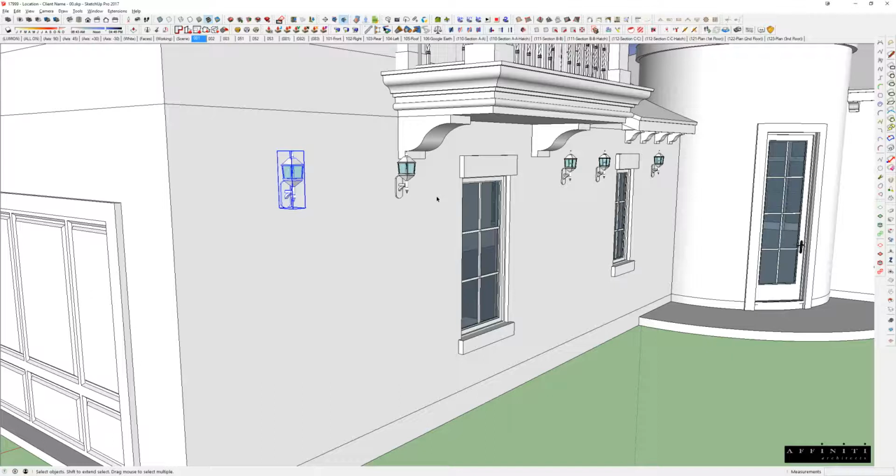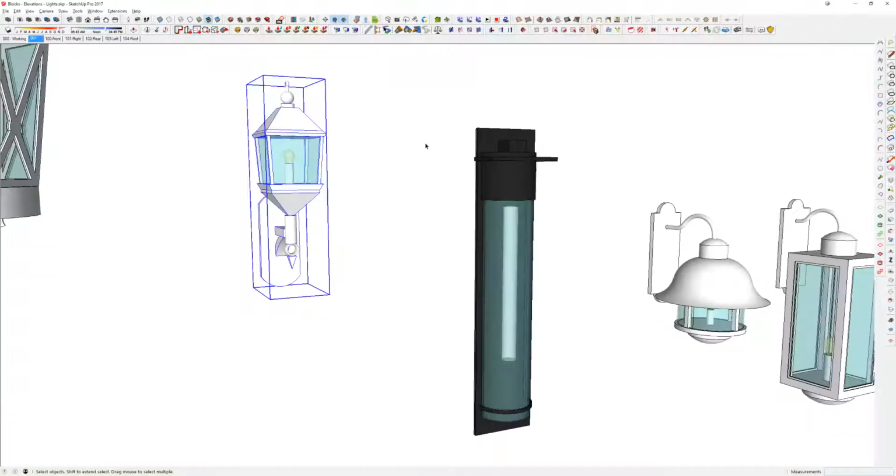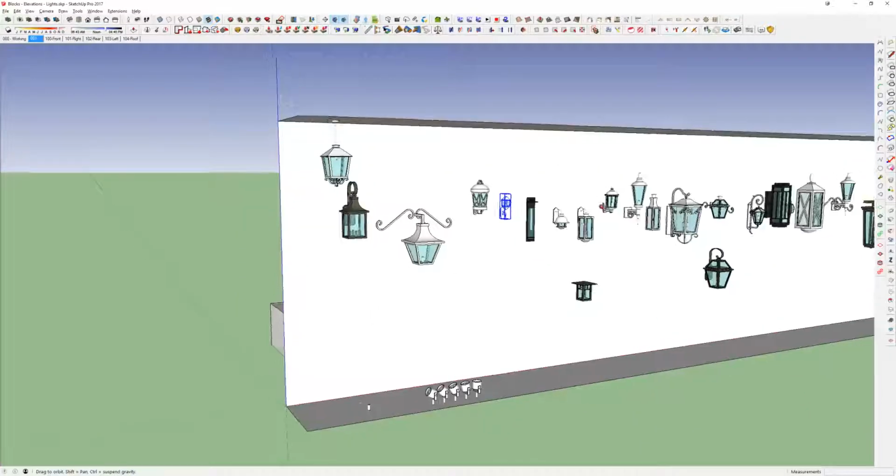You can bring their CAD blocks into your SketchUp model and then click on their oak tree symbol and say replace with oak tree 3D model, and every one of theirs gets repopulated. So you can actually populate your SketchUp model very, very quickly with accurate landscape that way. And that's something we're going to talk about once we get into site design and landscape stuff later on. But just one of those things to be aware of.